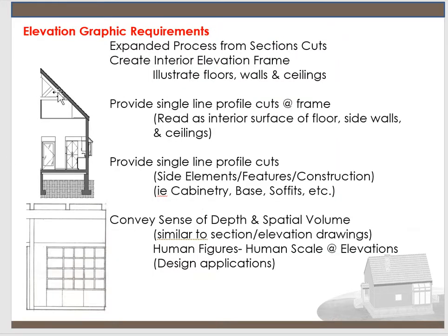So some of the graphic requirements, let's look at some of the elevations. So to expand the process from cut, so right here, this is an elevation, but this is special. This is a section. We're going to do that in a few weeks. This is really slicing like a piece of cake into the very ground. But certain things, they show certain things. So when you're creating an interior elevation frame, it's really important to thicken the walls here and show all of the windows and all your ceiling details here. And all these various lines represent something that's going on inside your space.